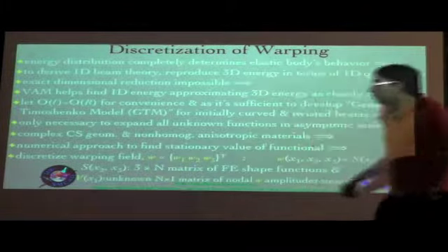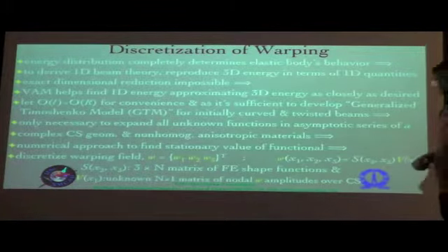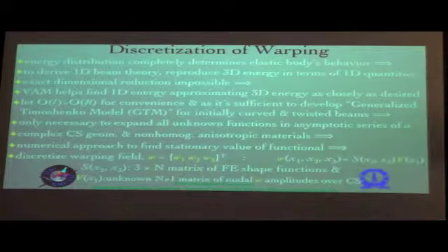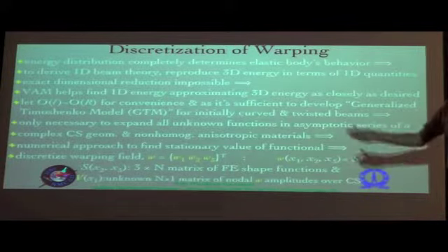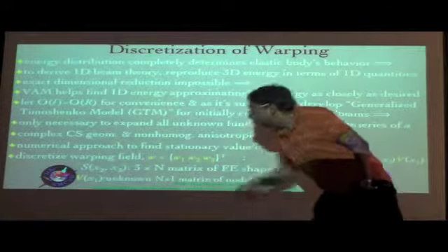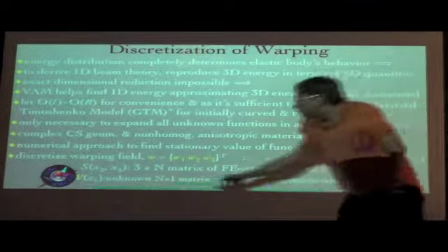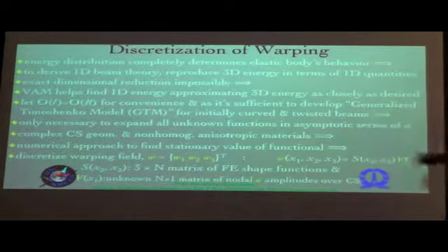Now what is this S of x2 comma x3? It is basically a matrix consisting of 3 by n, 3 rows and n columns that you have there. A matrix of finite element shape functions, just like you would do in any other 2D finite element discretization, depending upon the choice of the elements that you have made. Right. And of course the degrees of freedom at each of the nodes. Now V of x1 again is an unknown.